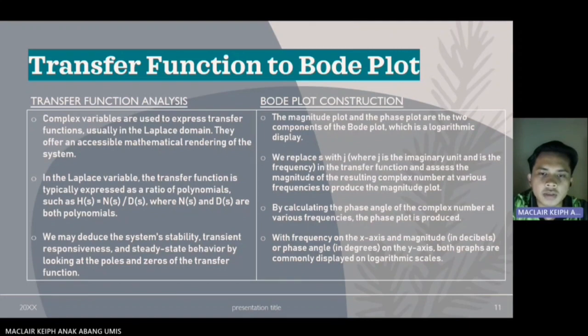By calculating the phase angle of the complex number at various frequencies, the phase plot is produced. With frequency on the x-axis, the magnitude in decibels, or the phase angle in degrees, is on the y-axis. Both graphs are commonly displayed on logarithmic scales.